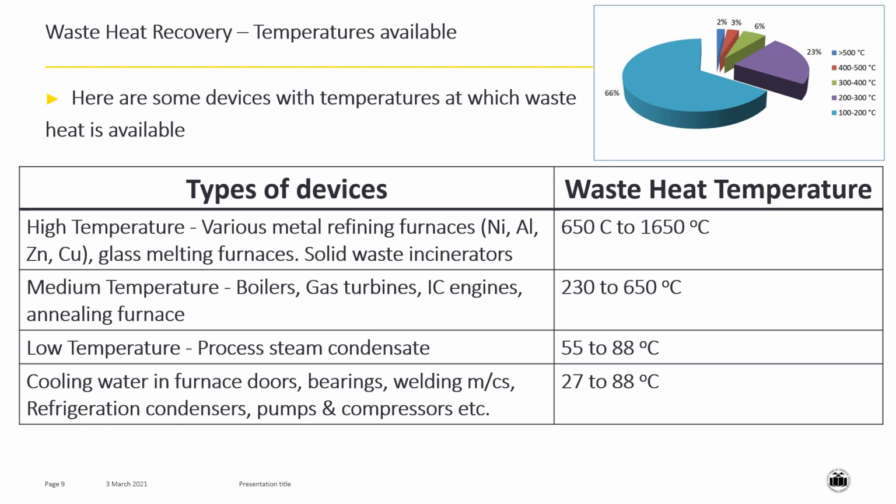Second class is medium temperature devices: boilers, gas turbines, internal combustion engines, annealing furnaces. Here waste heat is available at 230 to 650 degrees centigrade.